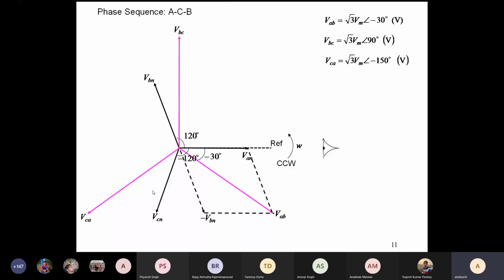But here, if you are given a phase sequence, you should write down the correct phase equations, and then find out the line values, and since everything is phasor, you have to be very correct in the magnitude as well as the angles. We'll do numericals on this actually.